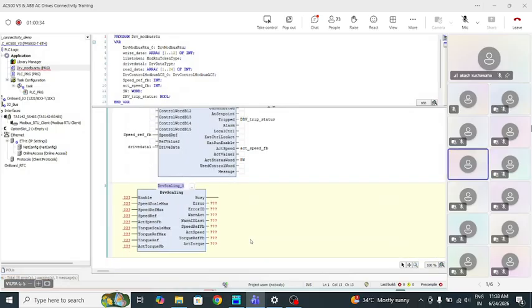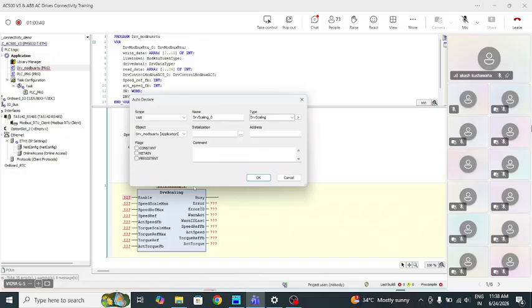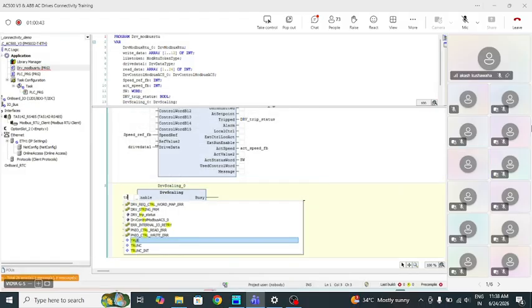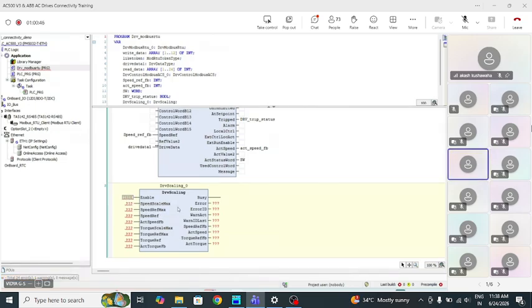It is very simple. There are ready-made function blocks. You need to just parameterize them. As mentioned earlier, it has a speed scaling of 0 to 20,000. So speed scale max will be 20,000. And this depends on whether your drive is in scalar mode or vector mode. In scalar mode, the drive will be in frequency mode, so here you need to enter 50 Hertz. In vector or DTC, it will be in RPM mode, so I need to enter the maximum speed required. This should be equal to your 46th group in speed scaling.